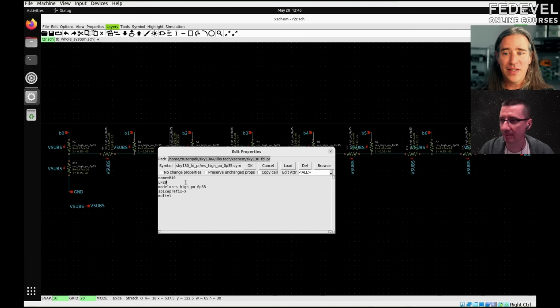But here's the thing. This isn't actually, now I know, the best way to do this. Normally what you want, because everything counts, and that's kind of the thing here. The Zero to ASIC course shows you the mechanics of making these things using XSchem and stuff, but it goes really deep. The resistor is a bit of polysilicon of a certain width and length, and it has an internal resistance that we estimate to be this. Great. But you're connecting to it on the ends, and that counts because we're down here and everything counts.